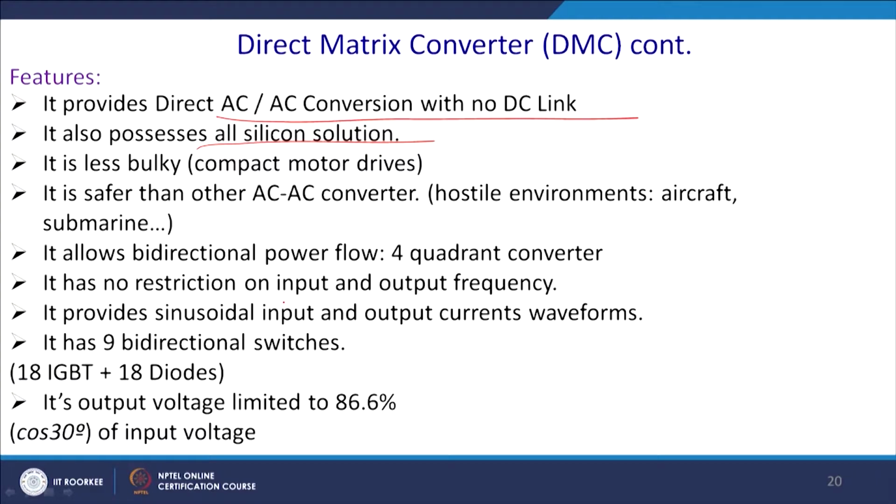If you choose silicon carbide based devices, you can run induction machines maybe as high as 1000 hertz instead of 50 hertz, and see what your power level will be. The same machine can straight away be increased to 2 times power.